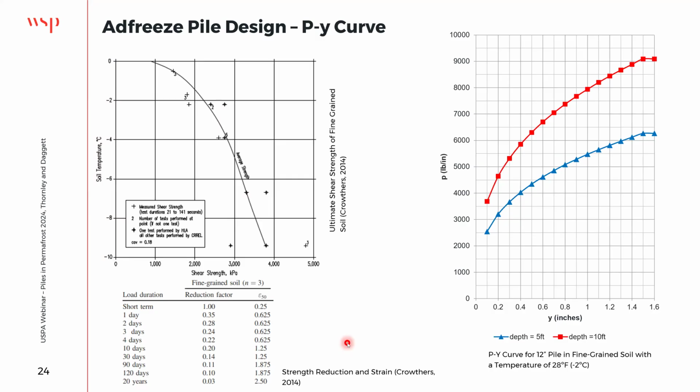And then you can get your reference strain, which is needed to calculate your p-y curve. With those two pieces of information, you can generate p-y curves to be used in a traditional lateral analysis.